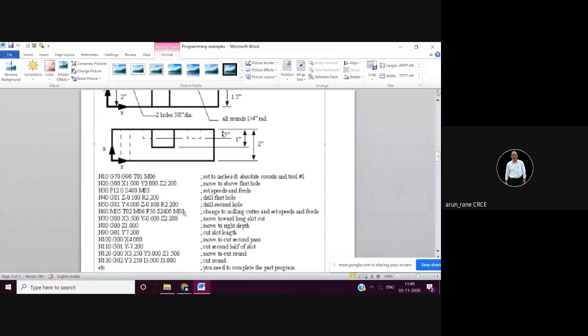You have given the RPM also, and on top of that you have written the feed also. So, my work is done: I started the spindle, changed the tool, and stopped the spindle. First it stops the RPM, then the tool change, and also the spindle start, but it is not possible. So here is how to do this: first you have to stop the spindle with M05. If coolant is on, then you have to say M09 in the next block.